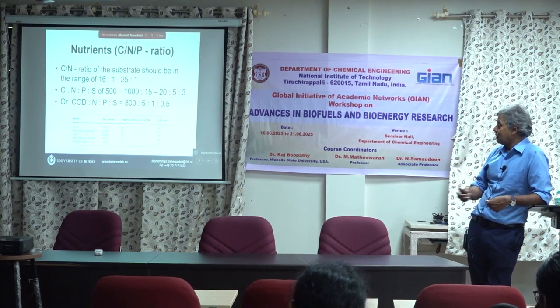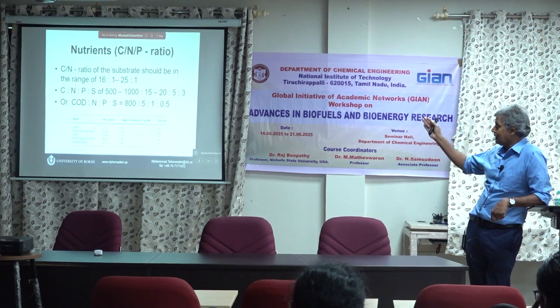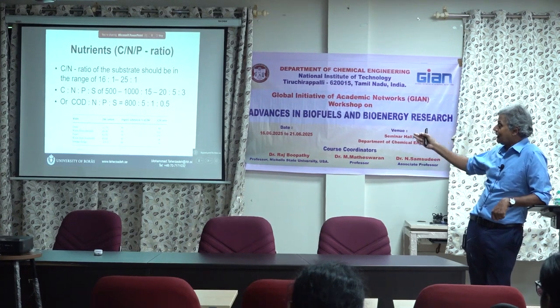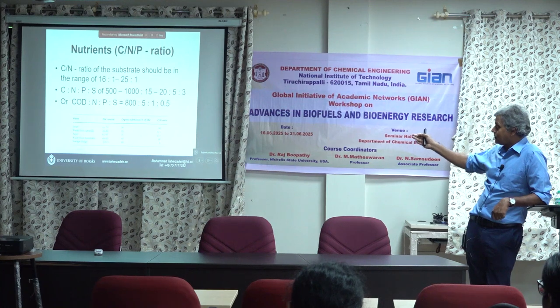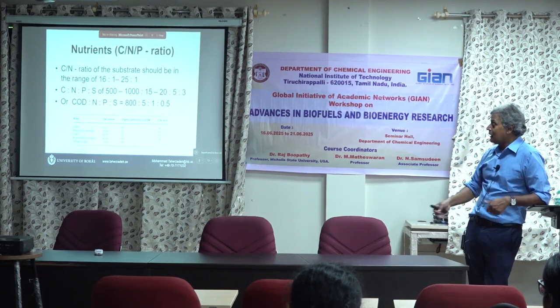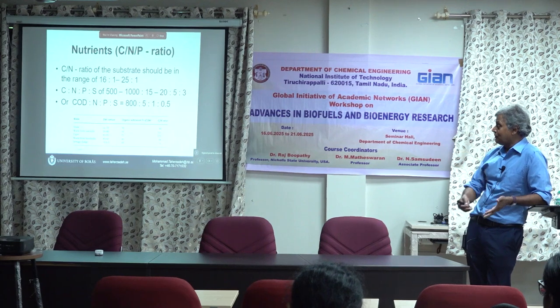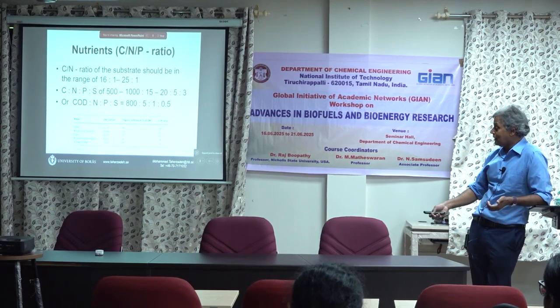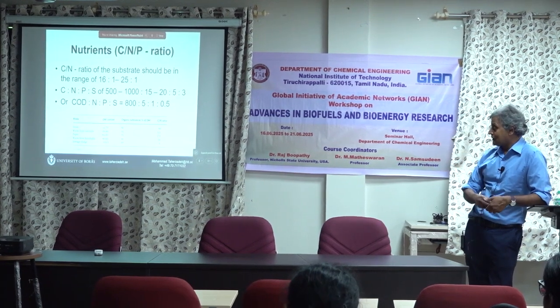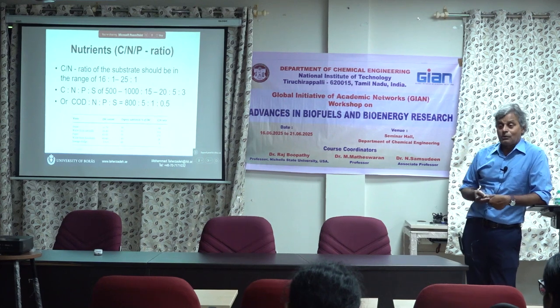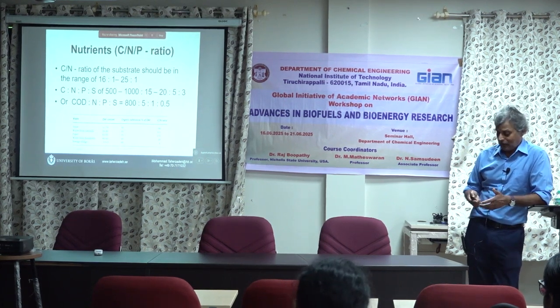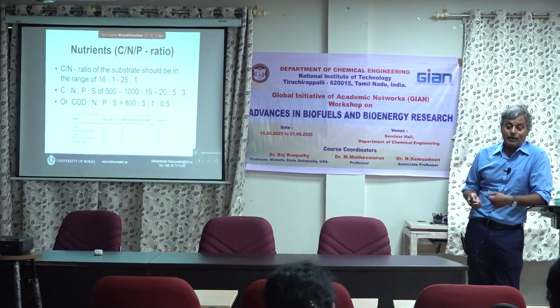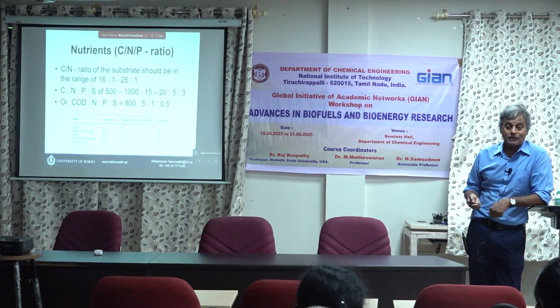You also have the waste material that you are using and the dry matter content, and it gives the organic carbon composition and the C/N ratio for each of them. There are examples if you are using straw as your substrate, if you are using paper as your substrate, if you are using sewage sludge as your substrate. I gave you examples of what your carbon nitrogen ratio should be. Okay, so these are all already perfected. You don't have to re-engineer this process.